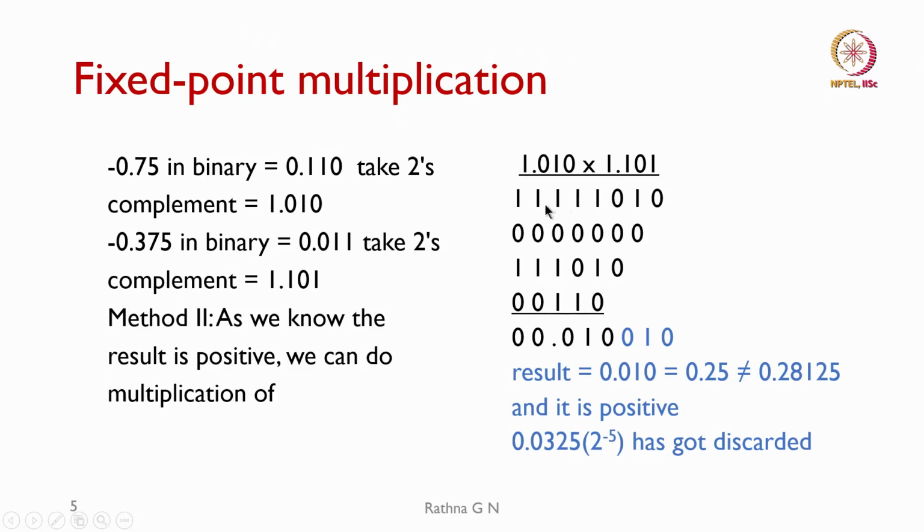We call it a sign bit extension in this case. So, although it is 1010, later on we will be putting it 1. When multiplying with 0, we need not bother, it is going to be 0. Again multiplying by 1, so we have done the sign extension with 1. And the last one, because this is the sign bit, what we are going to multiply with this number, we have to take the 2's complement of this number and then put it there.